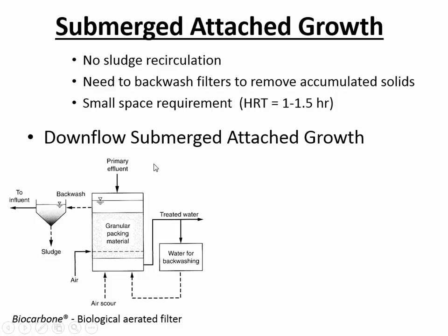This is kind of a treatment system that's similar to a drinking water filter. In drinking water treatment, after the water goes through coagulation and flocculation, it's put through a sand filter. The purpose of that is that the flocs will impact the sand grains and stick onto them.